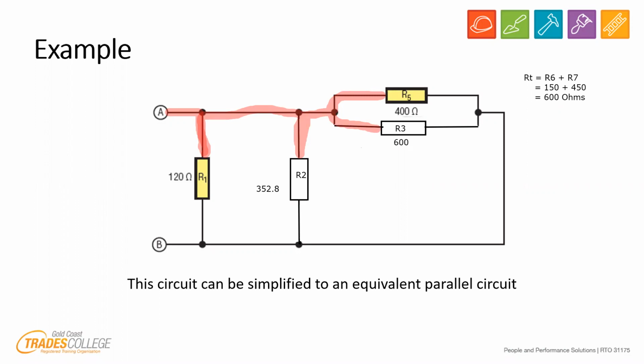And if I do the colors, actually what we do have now, I know it may not look like it, but if we understand the way things are connected, we do have a simplified parallel circuit. Can you see that one side of your resistor is connected to red, one side is connected to black? And there's nothing else in the way of any of these resistors.